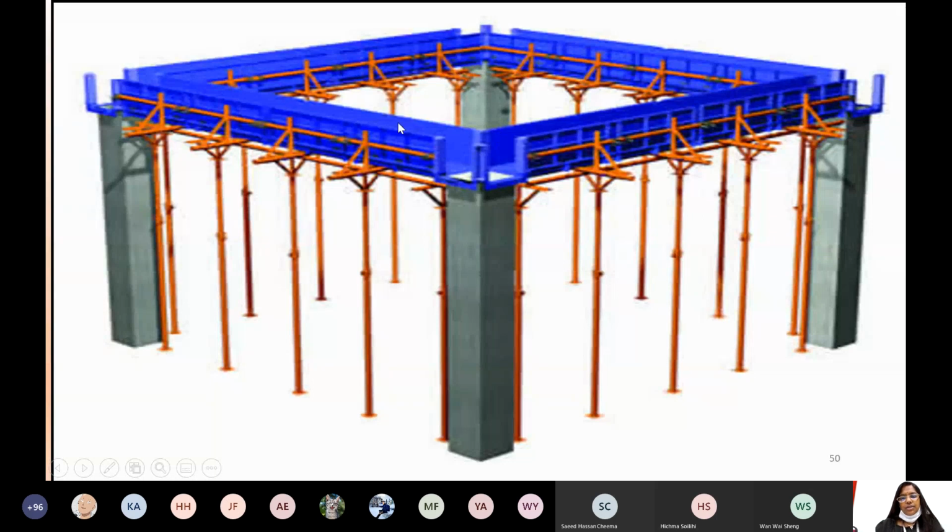Another type of beam again, this is showing a beam. They call this an N beam. A PVC type of formwork is used for construction of the beam. And see how they are supported. Again, they are using a T type of section and a pipe with a steel plate firm to the ground, just stuck to the ground, right? Maybe they use a bolt or another plate to support down. It is not really into the ground, just standing on the ground, supported on its own.